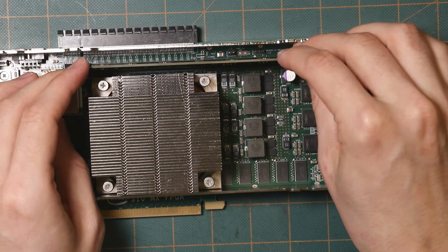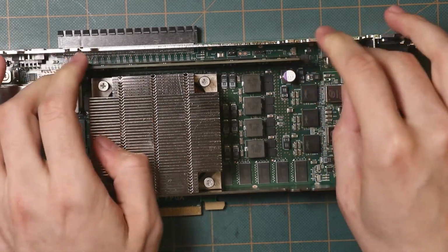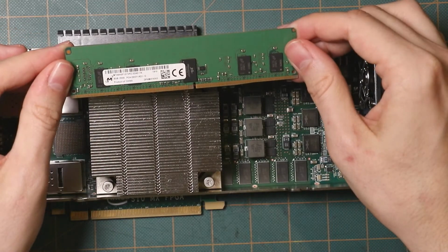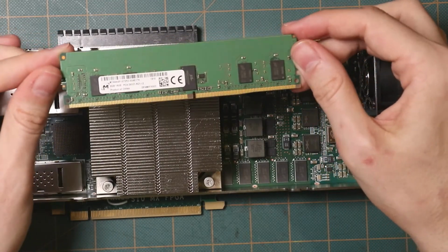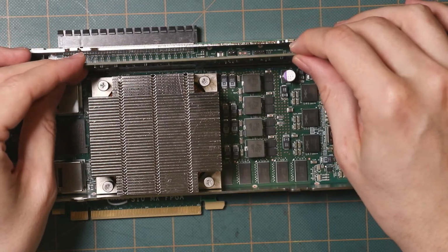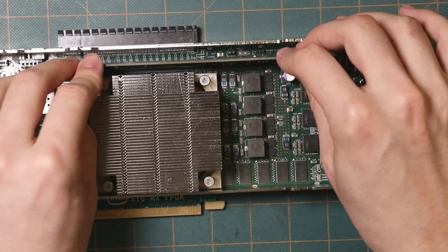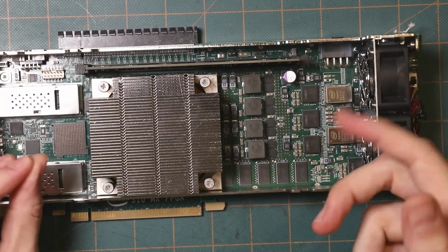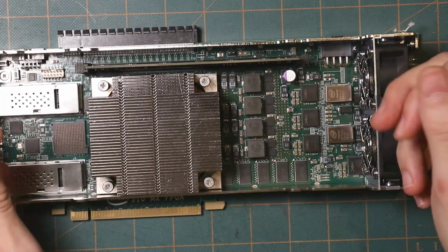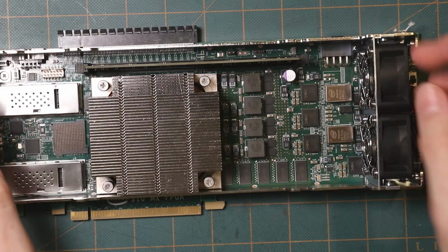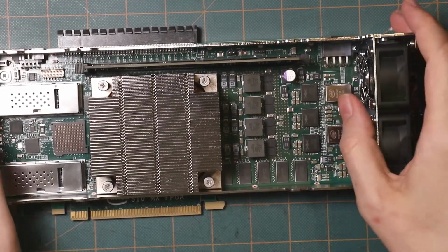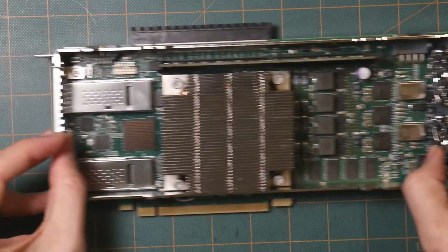You can probably get faster and larger memory modules. But one thing that's, hang on, this is 1R by 8, so this only has 1 rank on it, which I think is, I've noticed issues with the Xilinx FPGAs in terms of the number of ranks. If you have more than 1 rank, then the maximum frequency that the FPGA supports drops. I don't know why, but that's how it works. It's got to be for electrical reasons.